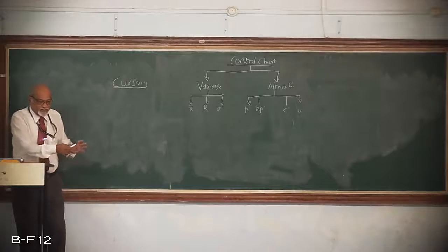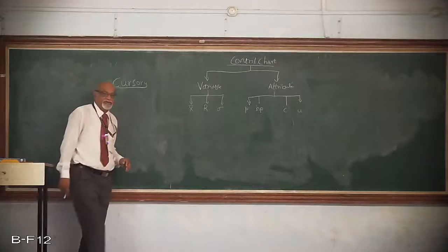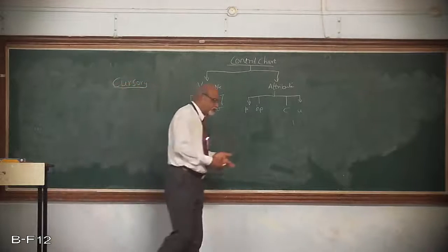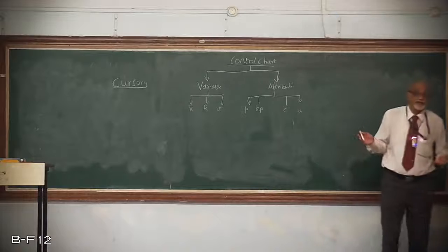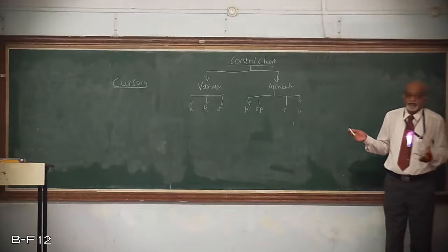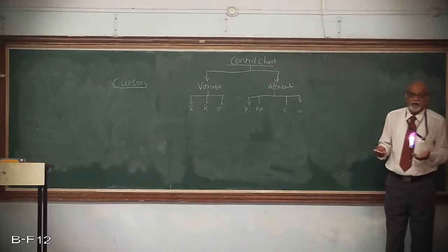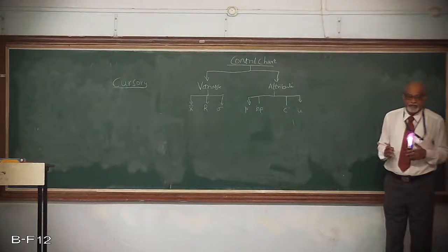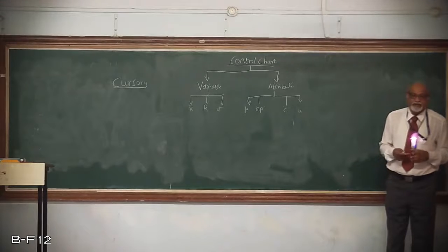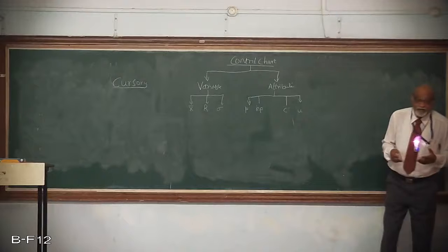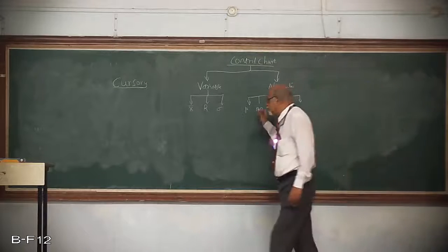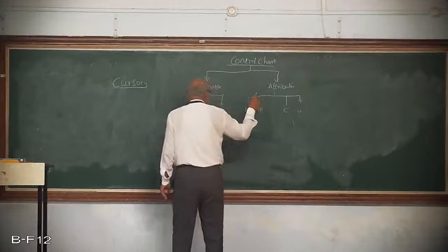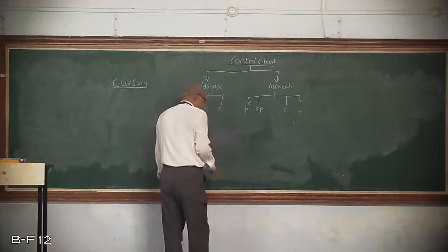These are certain advantages and disadvantages, and when to go for control charts for variables and when to go for control charts for attributes. Control charts for attributes are used when there are many quality characteristics, or some of them may not be possible to measure. And the third aspect, the most important, is the economical aspect. Okay? The control chart for attributes will cost less.